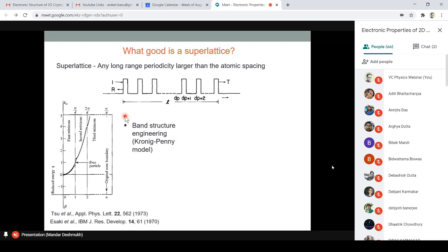and once people found semiconductors and other materials, they wanted to tailor to their requirement some electronic property. Because if you have a material, let's say silicon, it doesn't have all the desirable properties. Or gallium arsenide, which is a cousin of silicon made using gallium and arsenic. So, one way to engineer or tailor desirable properties was to make regions of different semiconductor alternating, and that actually is a way to realize this periodic lattice, and this periodicity does the job of reflecting the electronic waves or scattering them, and gives rise to new band gaps in semiconductors.